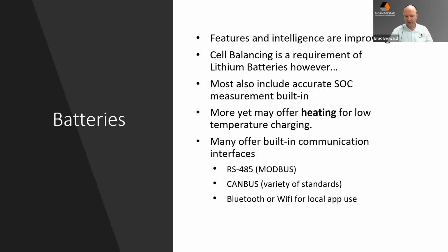We're also seeing, of special note for off-grid markets such as ours and our customers, a little more lithium capability that has heating built into the battery. That's going to be driven by the need for off-grid sites in the northern parts of the country, even in Canada, where you have sub-zero temperatures, and that lithium battery doesn't have to get warm, but it has to get at least to the point that it's not below freezing for it to actually receive charge. As I said earlier, with electric vehicles it's the same kind of requirement. You've got to do that preheating of the battery before it can accept charge.